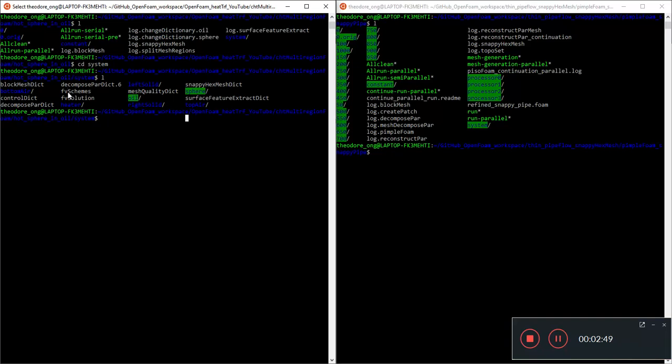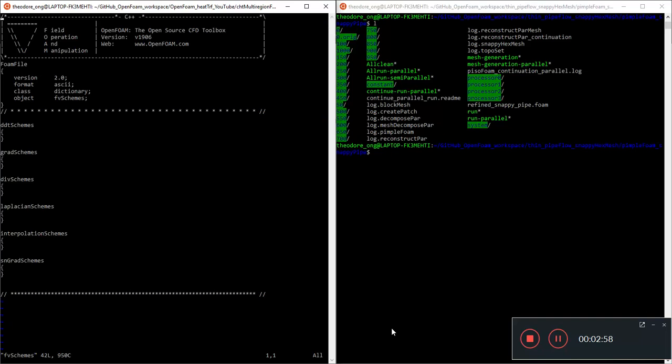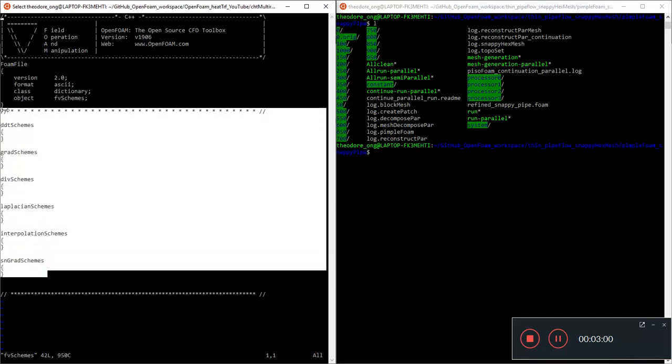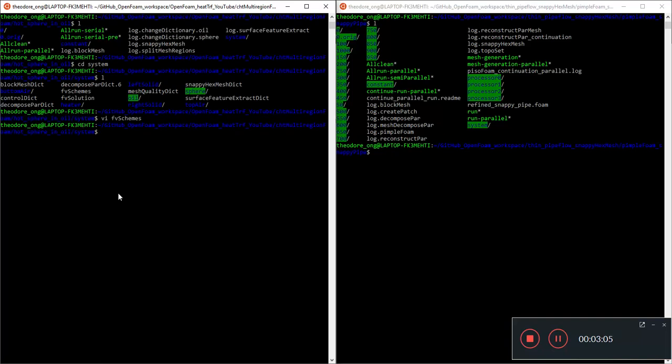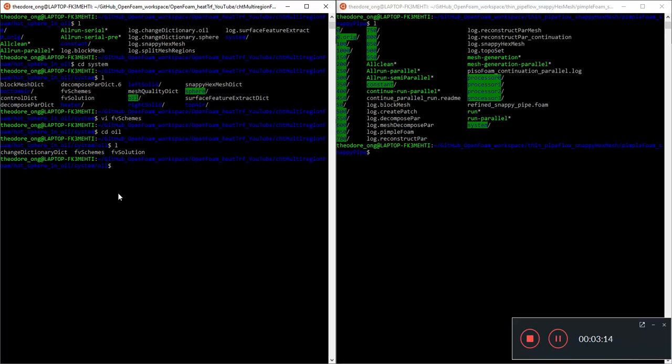Obviously there's an fvSchemes and fvSolution here, but as we discussed a few videos before, there's basically no information here whatsoever, so we don't need to worry about filling these in. We'll just leave it there as it is. But let's go for the oil one first. So there are three files here: changeDictionary, fvSchemes, and fvSolution.